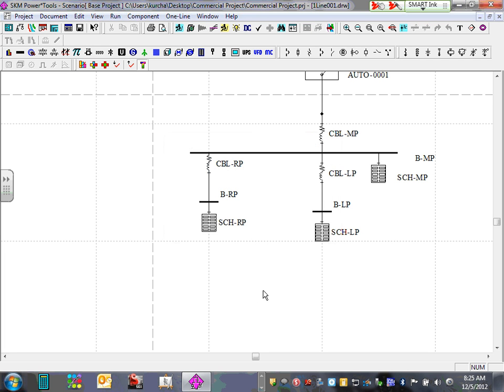When you use this software, every bus, every schedule, every cable is a unique entity. You cannot give them the same name. Otherwise, remember, you're doing analysis on these. You're going to have short circuit. You can't have a short circuit on two components that have the same name. It confuses the software when it does the calculation. It has to be a unique name, unique by a 0 or a 1 or acronym. Cool? I need thumbs up when everybody has built the system. Everybody built that component? Okay.